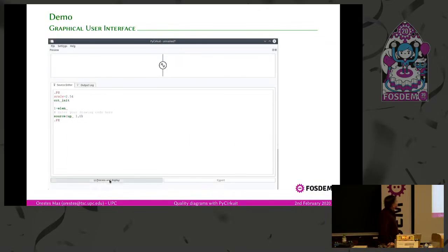So you can change, for instance, in this case, to a square wave. We can apply a label. In this case, the label is a left label, because going up, the label is on your left hand, and it accepts three parameters, A, B, C, that go into the bottom, center, and upper positions. So you can change those to the symbols to specify the voltage.